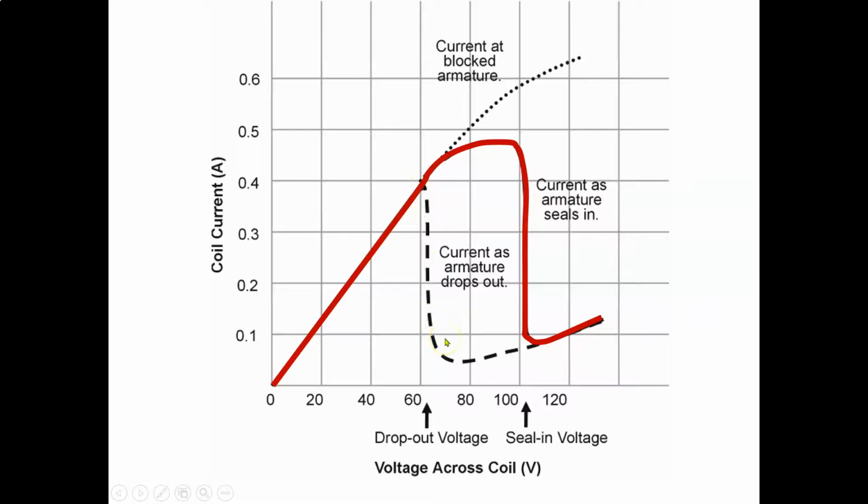So at 50%, your voltage is at 50% now, so your current's not going to be super high. It's not like it's at its maximum value at 120 volts. It's dropping down rapidly to 0 here. Once it hits 50%, the armature is going to open up. Yes, the flux path is going to increase, but your current is already on its way down, so we don't really have to worry about that.